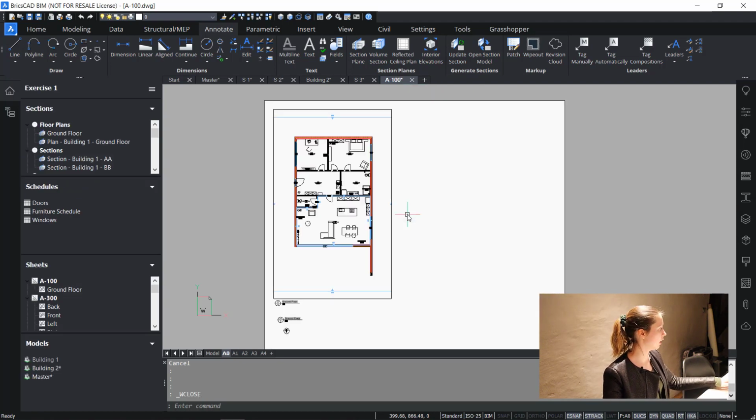And again, I will sum up what you can store. You can store title blocks, layers, colors that you imported, line types that you imported, hatch patterns that you imported, blocks that you created, text styles, dimension styles, and page setups. So basically a lot that you can specify. So certainly worth taking a look at if you want to customize your entire drawing process. A drawing template could be the solution for you.